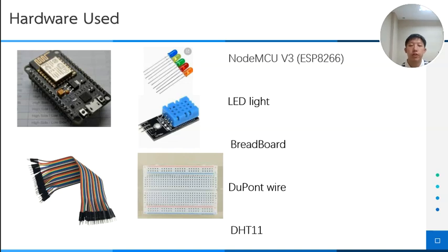In terms of hardware connection, we adopt a simple and reliable wiring method. The GPIO interface of the ESP32 is connected to the data pin of the DHT11 sensor, and the control pins of the white LED and the green LED respectively through Dupont wires. At the same time, ensure that the power and the ground pins are connected correctly to avoid short circuits or poor contact.